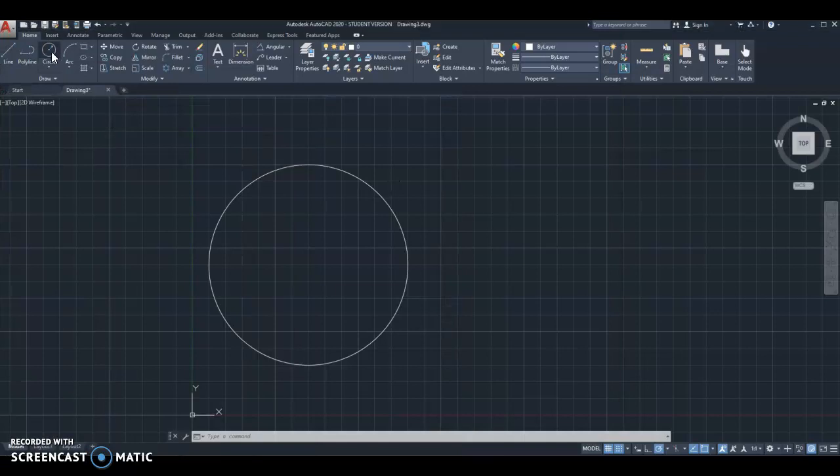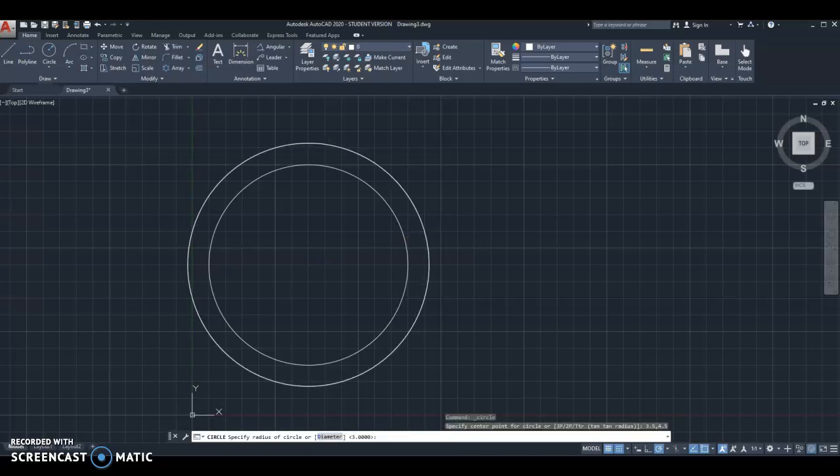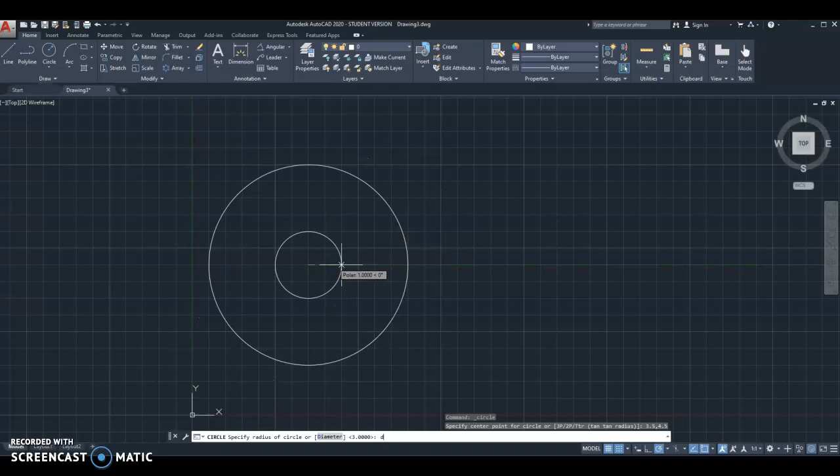So I'm just going to finish this front view of the circle. I'm going to make another circle, and I can again key in the center 3.5, comma 4.5, and I have a D diameter of 4.